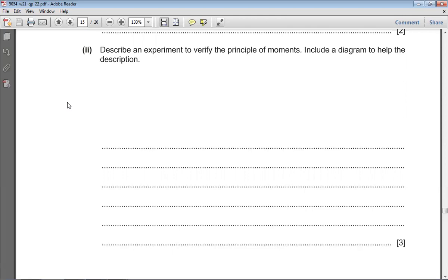The methodology is very simple. You take a scale and put a pivot under the center of the scale. Then you take 2 known loads, where you know their weight. You hang 1 load on the left side of the pivot and 1 load on the right side. Then you move those loads by the hit and try method, until the ruler is in equilibrium, balanced on the pivot.